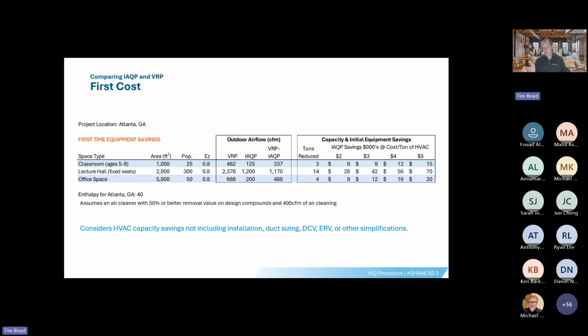Notice 5,000 square feet. So probably not dissimilar to the types of spaces you guys work in every day. And again, about 4 tons can come off that space. For the market you live in, you also get an enormous heating savings here. We're not showing the heating, but I'm showing this in tonnage, obviously. But think about your heating savings. If you can lower that outdoor air, you lessen the preheat requirement. You also improve the mixed air temperature. You improve the humidity during the winter. So all those benefits are also added and not shown here as a first cost savings or an overall benefit